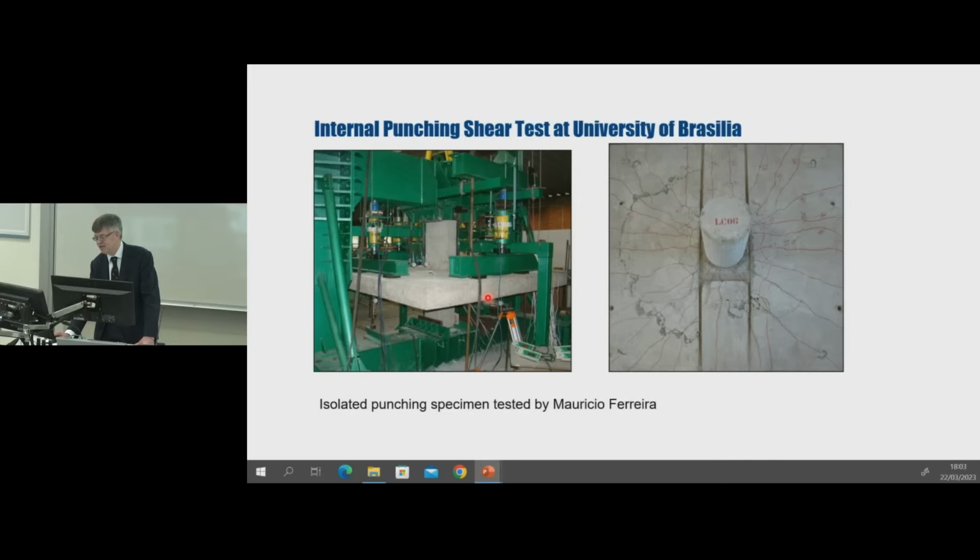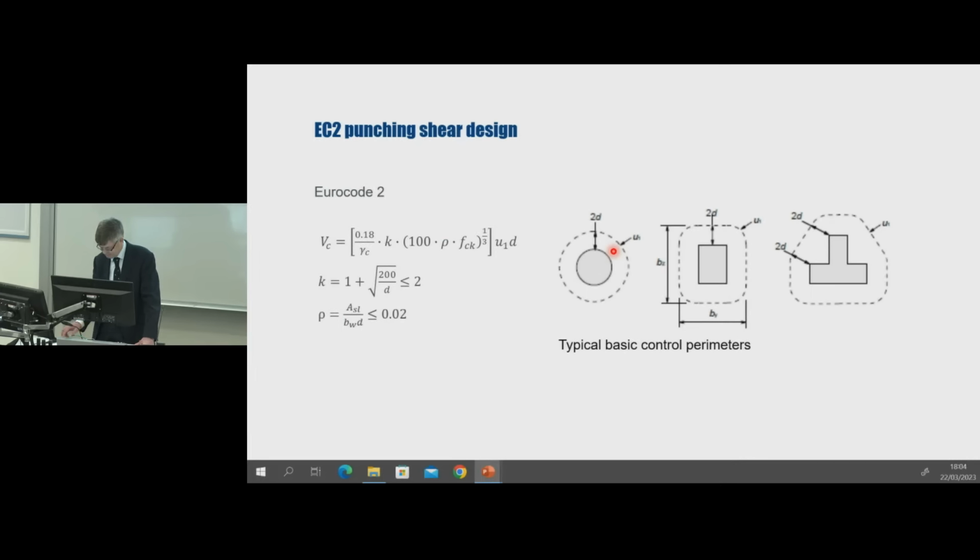In a punching shear test, the slab is typically supported at its center, either on a bearing plate or a column as shown here, and then we load the slab around its perimeter, typically with 8 equal point loads. Under load, radial and circumferential cracks develop as shown, and we increase the loads until punching failure occurs.